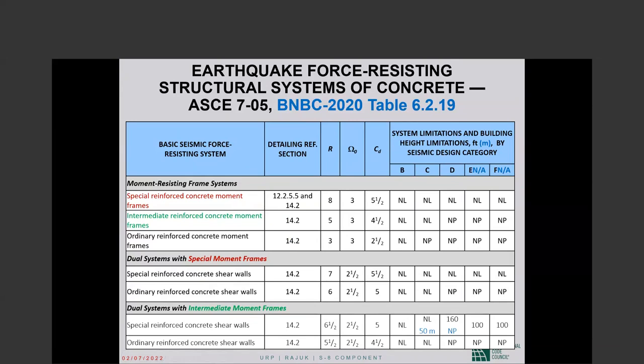there are height limits on almost all structural systems, with the exception of special moment frames of concrete and steel and dual systems utilizing special moment frames. Those are the only systems without height limits on them. Every other system has a height limit on it, and most of the time the height limits are in the higher design categories, not so much on B. Design categories E and F, I have mentioned repeatedly, do not exist in Bangladesh.